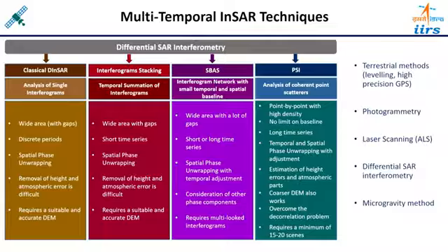This technique also requires a very accurate DEM. If you do not have a very high resolution DEM, the accuracy of measurement of classical InSAR will be poor.